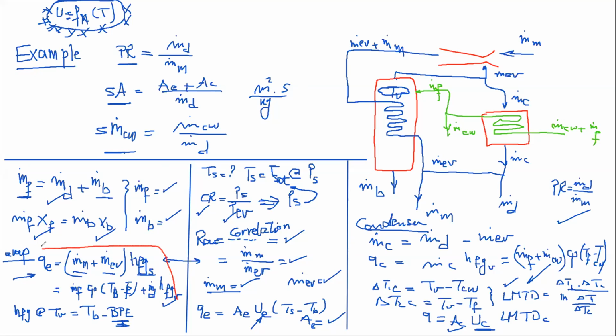Yeah. Look at the figure. What is entering here is basically m dot steam. In our case, the steam which is coming here is a combination of two components, entrained vapor and motive steam that are mixed together here. So this is going to condense inside the tubes and give off the latent heat. The Q given in the evaporator is nothing but this quantity multiplied by HFG of steam. This is energy added by the steam.